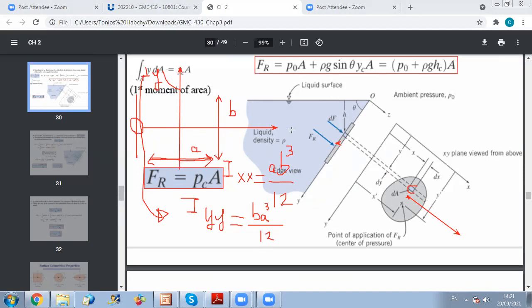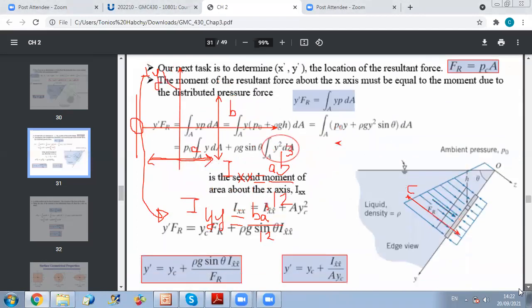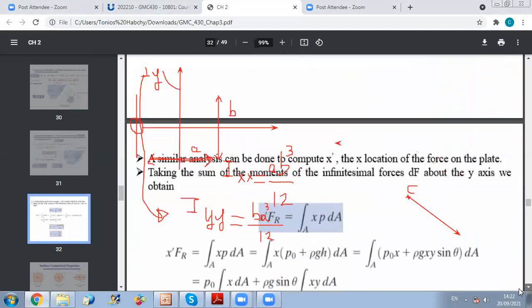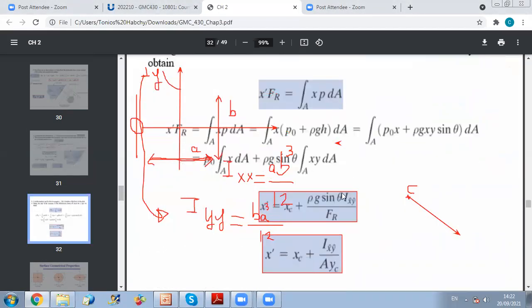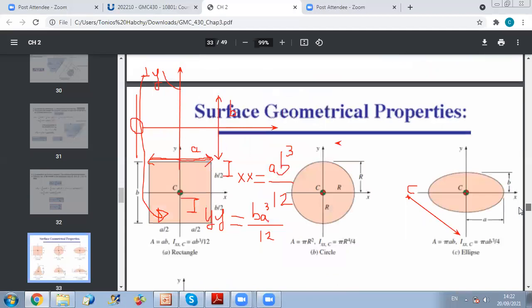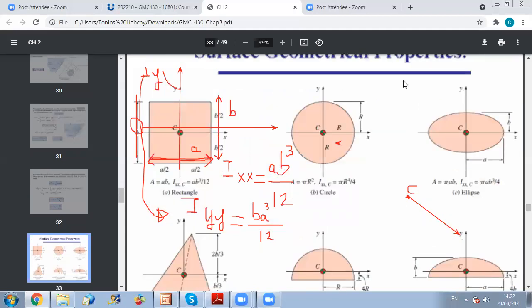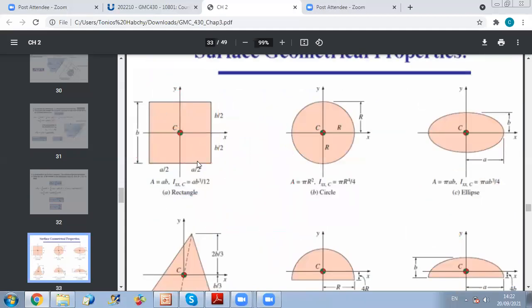Now, what is also interesting for us in the formula, we need the value of Ix, but also the value of the product Ixy. What is nice is that Ixy is 0 whenever I have a symmetrical axis. So if the x-axis or y-axis is an axis of symmetry of the geometry, automatically Ixy, the product, is 0.